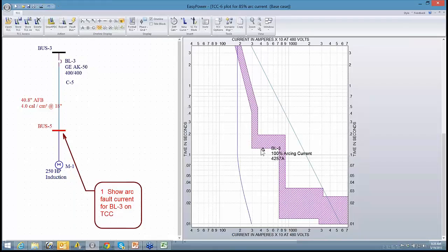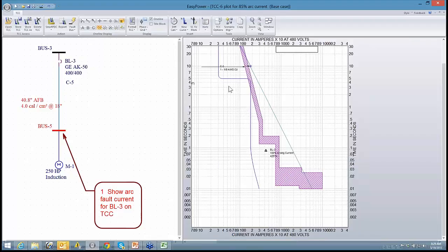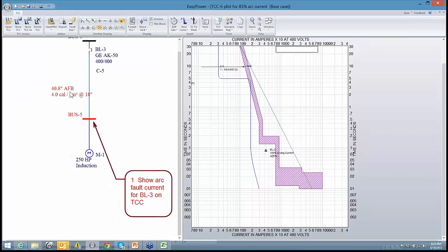and make sure that the 85% of the arc current is clear of this particular knee in the curve. So here now, as far as worst case calculations with this particular setting, the breaker has a potential for still engaging at the same point, 130 milliseconds, but it looks like it's guaranteed to clear well before the 200 millisecond point. Okay, all that can be derived and displayed visually and is important for anyone trying to do mitigation and coordination for any downstream load.